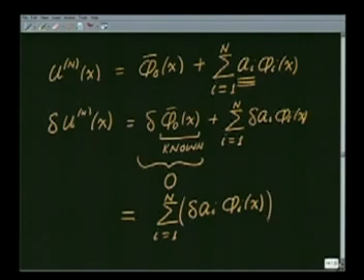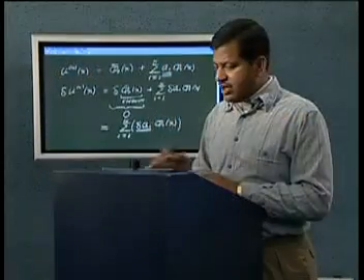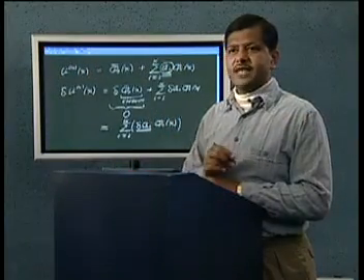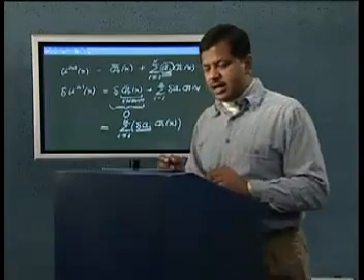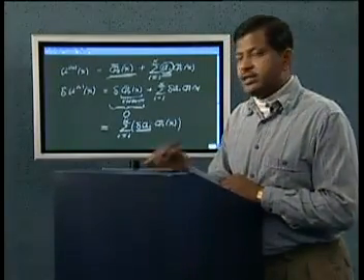By putting it back in the principle of virtual work or the variational formulation that we have made, and by choosing particular values for these delta ai's, we will now get n equations in terms of the n unknown coefficients ai, exactly the way we have done earlier. The only difference will be that your un will carry this expression.